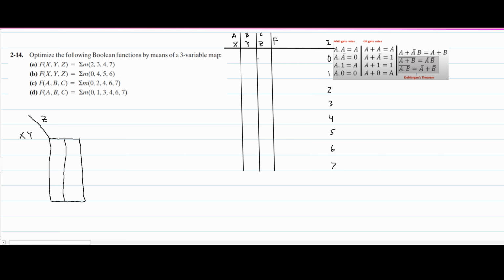Now, what we're going to want to do is have all the different possible types. Our z is going to be 0 and 1. Those are the only 2 possible types. So when we look at our truth table, we're going to fill in 0, 1, 0, 1, 0, 1, all the way down the column. When we look at our x, y, the different types we can have here we know are 0, 0, 0, 1, 1, 0, 1, 1.